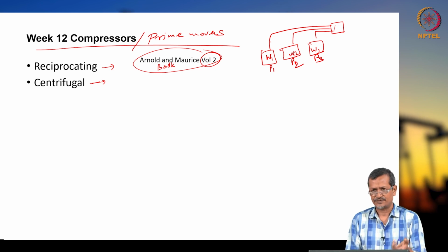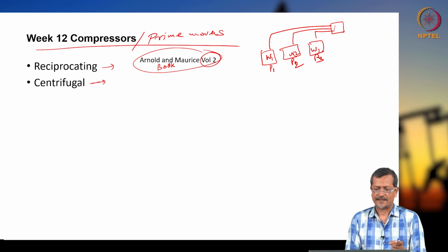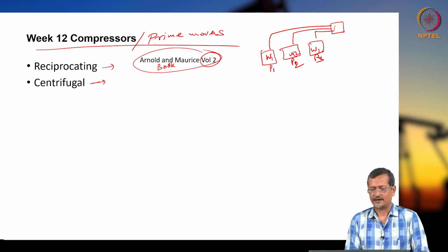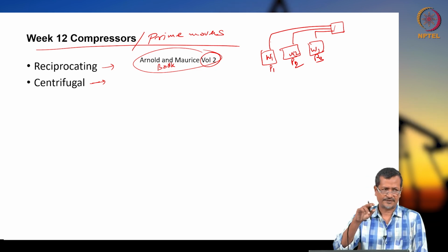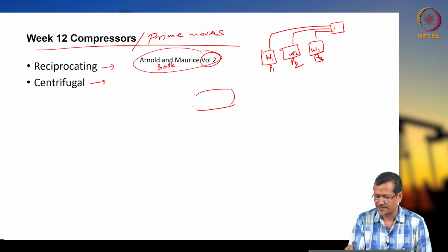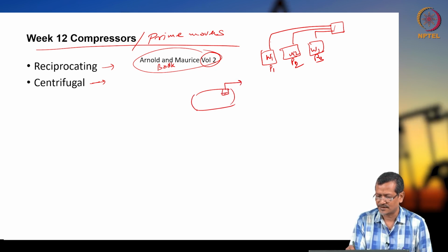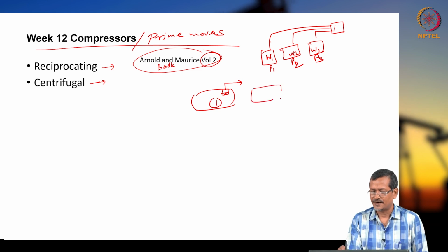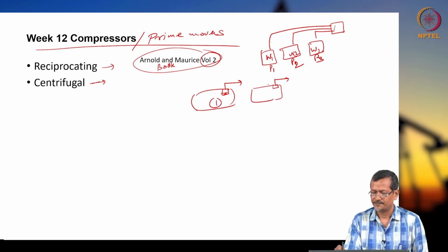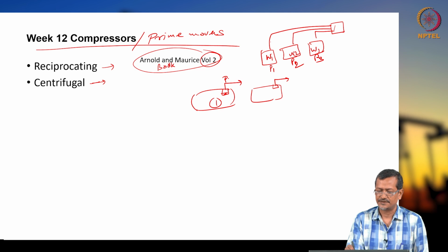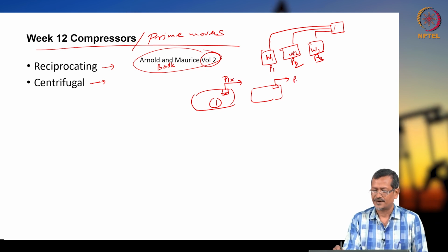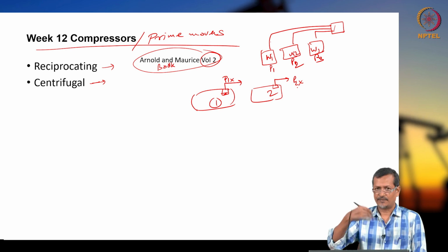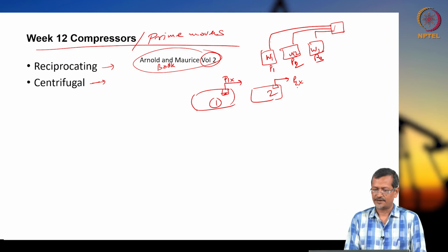In gas lifting systems, you need to compress gas, since different wellbores have different pressures. Each separator will have a gas outlet line, right? Separator 1 may be high pressure, and separator 2 may have much lower pressure, because pressure goes down at each stage.